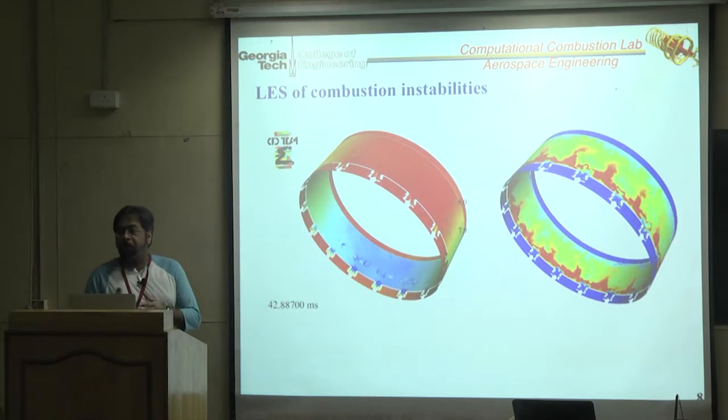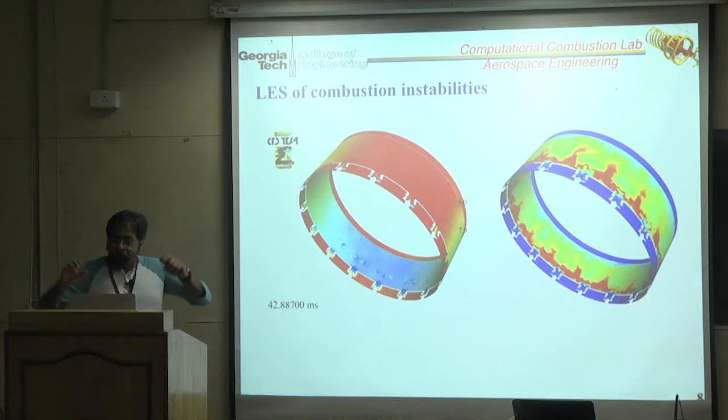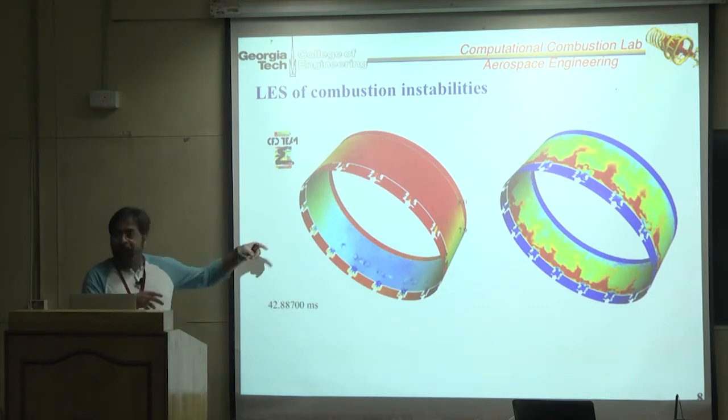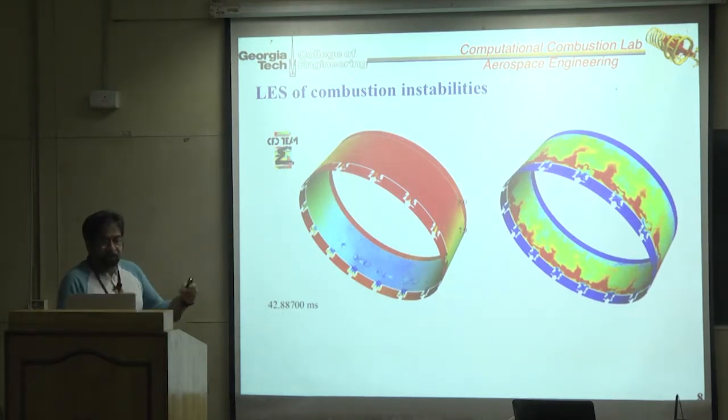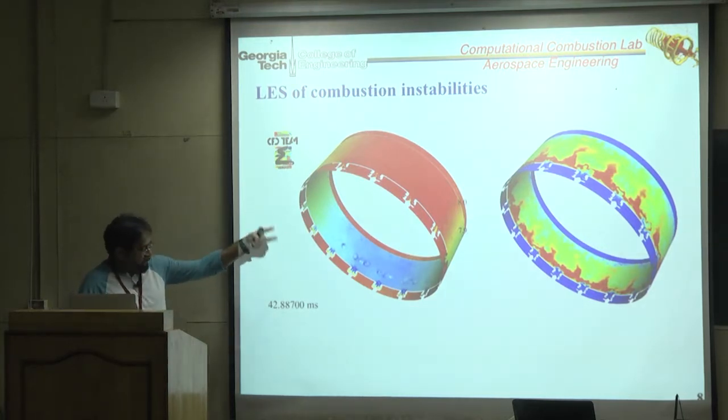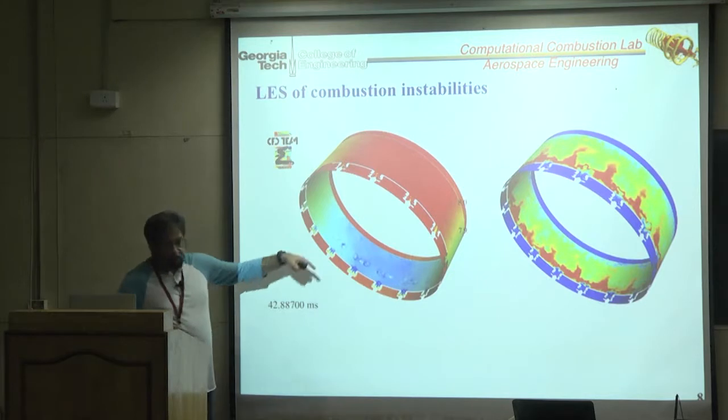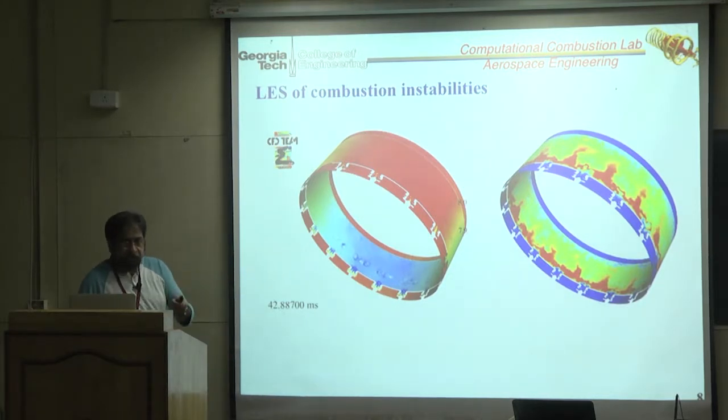Yeah, I mean rocket engines do that a lot too. But the problem, from a prediction point of view, is that if you change the design, you'll have to do the experiment again to find out how to do that. And the question was that if you can do that numerically, then it's easier to play around with this without building anything, right? And then you can figure out whether you can get sustained stability. But this problem is very difficult, computationally and experimentally. The interesting aspect is that azimuthal instability is the fundamental instability of interest. Longitudinal ones used to be important in the old ramjet type problems, but not for gas turbines. It's the azimuthal ones, and in rockets also, it's the azimuthal instability that becomes severe.